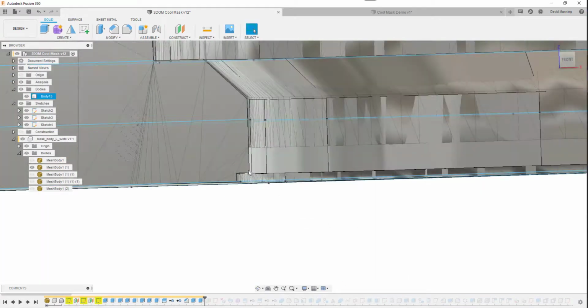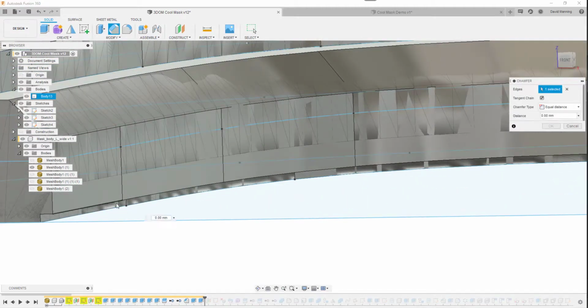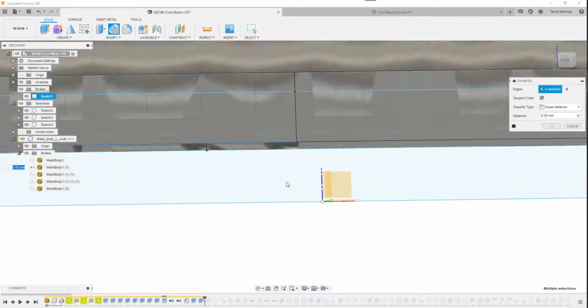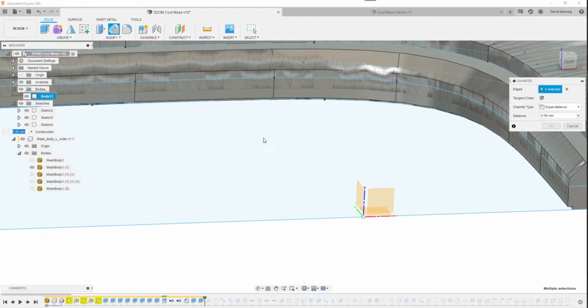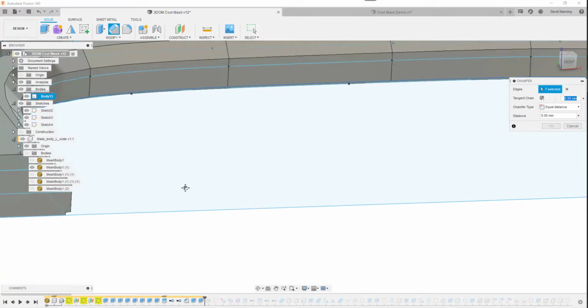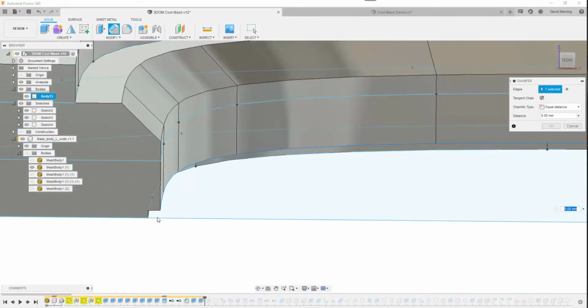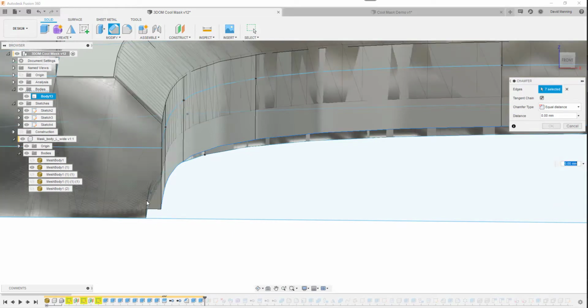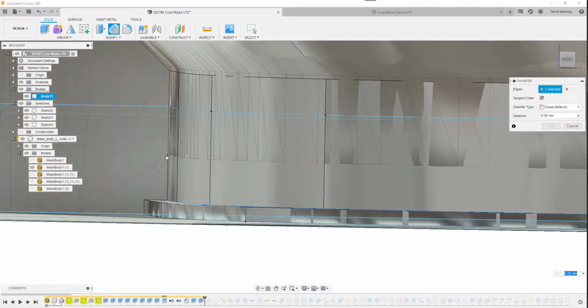Now I did struggle. I had originally wanted to simply chamfer this edge here. So for example, if I grab that and go around, I should turn that mesh off because that's just going to confuse things. Zoom out a little bit, orbit a little bit, keep selecting this outside edge. What I want to do, let's turn that mesh off for the time being, is chamfer that down. Now it's not an even chamfer. You can see if I turn that mesh back on again, the dimension there is longer than that dimension there.